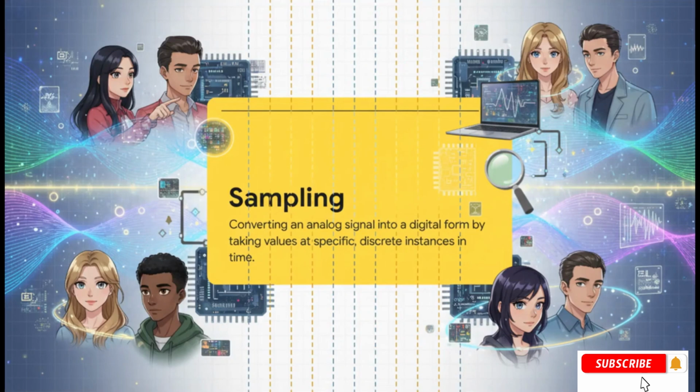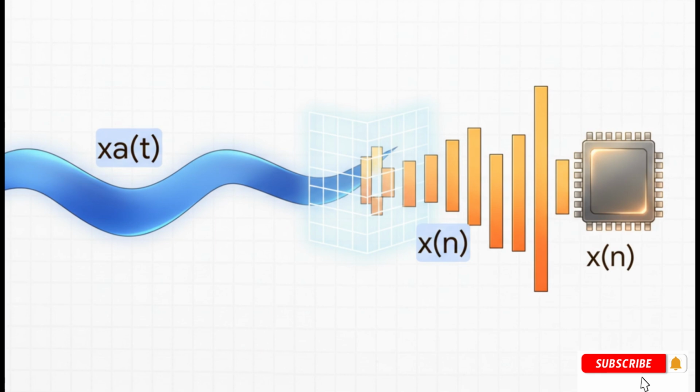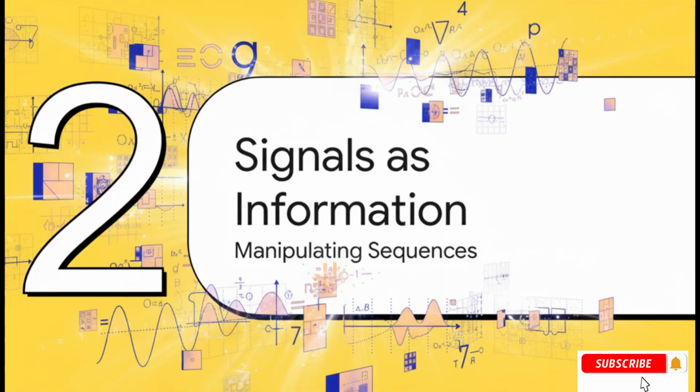So to get that wave into a computer, we have to do something called sampling. It's a really crucial step. Think of it like taking a series of snapshots of the wave at perfectly regular intervals. Instead of trying to capture the whole infinite wave, we're just grabbing a set of measurements that represent it. And boom, this is what you get. That smooth wave, x of t, has been transformed into a discrete time signal, x of n. It's not a continuous line anymore. Now it's just a sequence of individual values, a list of numbers, and that is something a computer can finally get to work on.